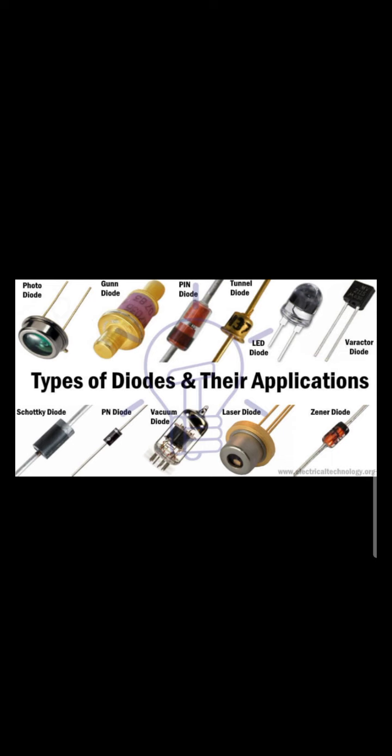This anode and cathode are based upon the potential difference between the two terminals of the given source, like a battery or electric source. Okay, diodes can be classified in this way into two types. If the anode has a higher potential than the cathode, then such a diode is said to be forward biased, and it allows the current to flow.